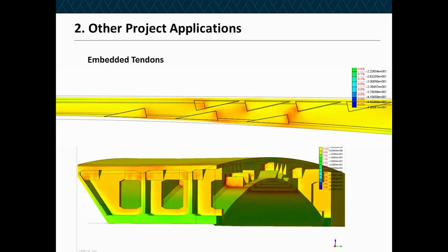And you can see here these areas of orange indicate a tensile stress between the two blisters. So because of the proximity of the blisters to one another, top and bottom, we were able to determine that they were effectively trying to pull the bridge apart in those locations, and that was not a factor that had been considered in the original design or the original reinforcement layout.